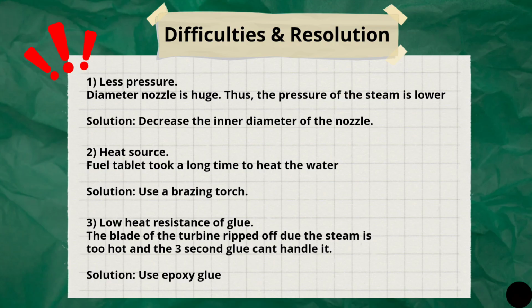We encountered several challenges during this project. First and foremost, low steam pressure. The initial nozzle diameter was too large, resulting in low steam pressure. To solve it, we reduced the inner diameter of the nozzle to increase the steam pressure produced.